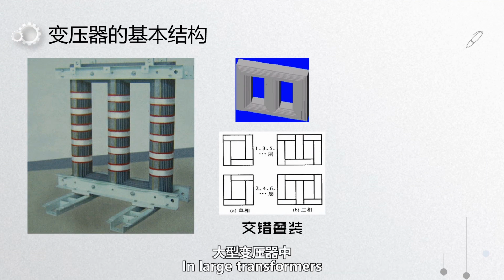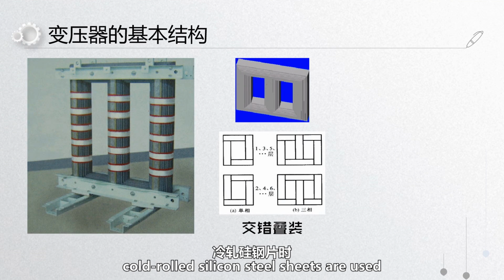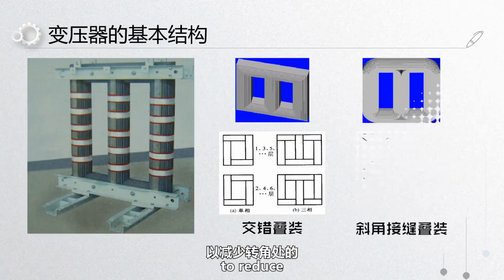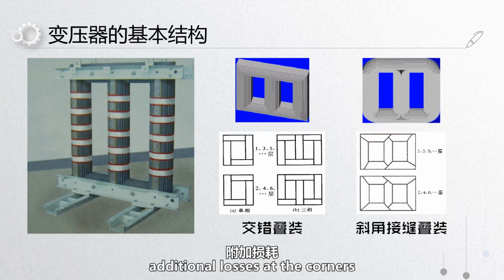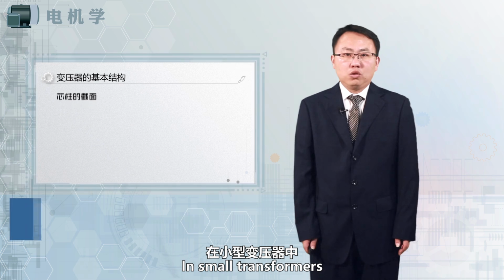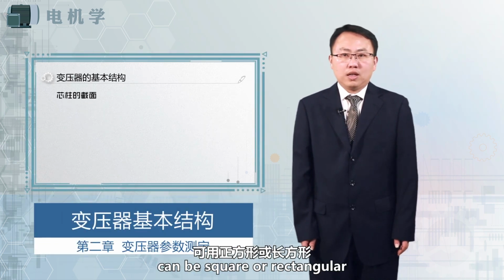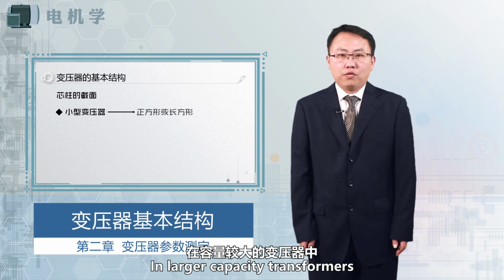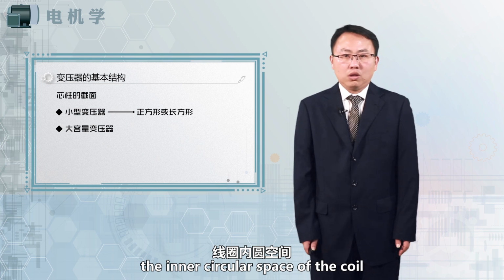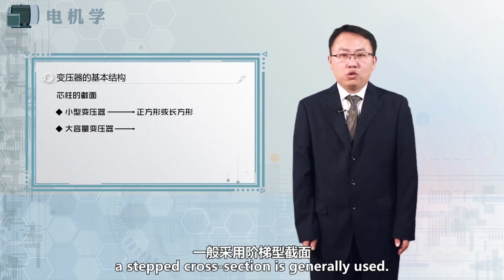In large transformers, high magnetic permeability and low loss cold-rolled silicon steel sheets are used with slanted cut sheets to reduce additional losses at the corners. The cross-sectional shape of the core column in small transformers can be square or rectangle. In large capacity transformers, to fully utilize the inner circular space of the coil, a stepped cross-section is generally used.